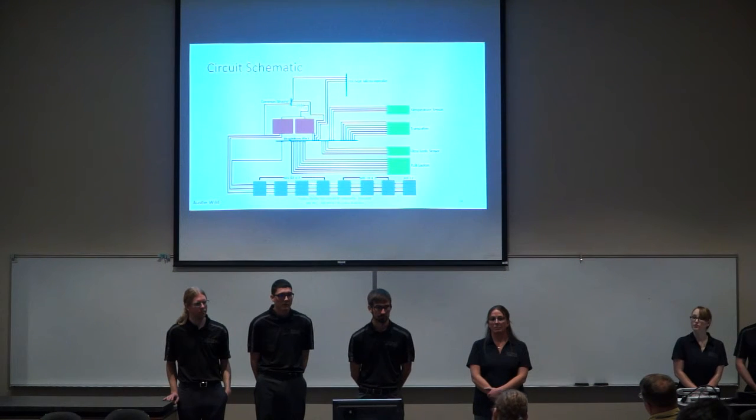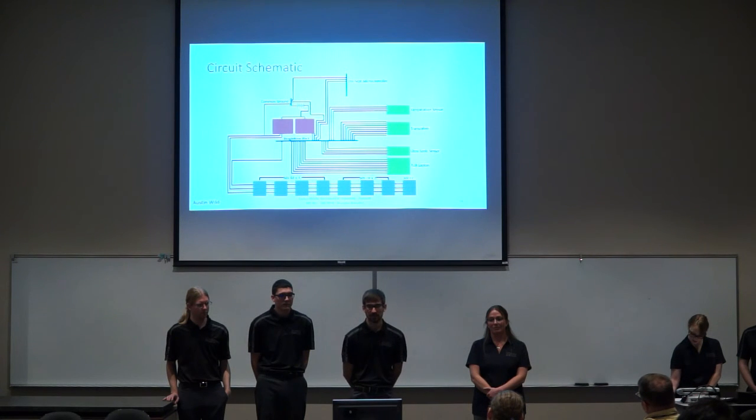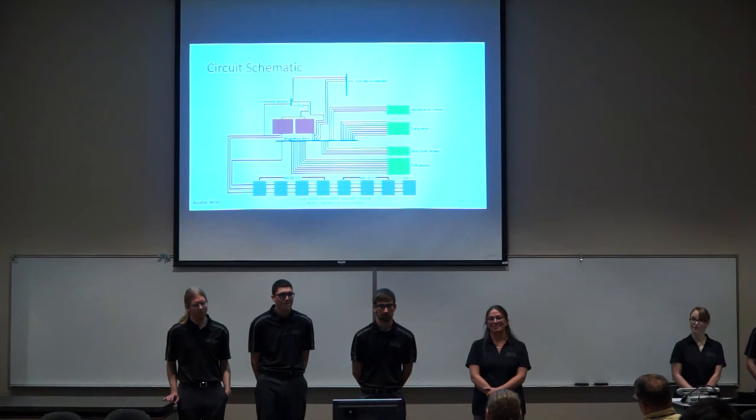Okay, it's interesting that you mentioned analog to digital converter, because when you talk about the BeagleBone Black, that's one subsystem that you don't even mention. But it is present there. If you use a 5-volt, a ground and an analog, which makes sense, will you need any additional components for that to function? According to what I've seen on the spec sheet, I do not believe so. Then you believe incorrectly. You will need many additional components for that to function. And so that's why we want to see a schematic.